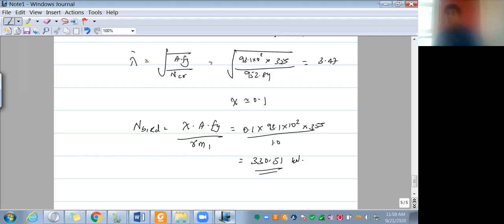So in any member which is under compression and not restrained, for example, if the column is supported by walls on all four sides, it will not have any such failures because there won't be any buckling. But if it is free to buckle, so that is why Le means effective length. So Le indicates that the effective length means there are only supports at 9-meter interval.